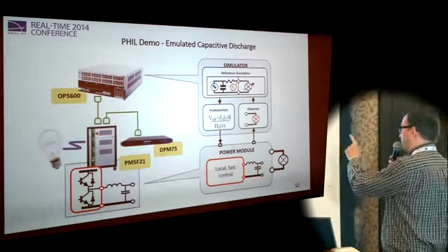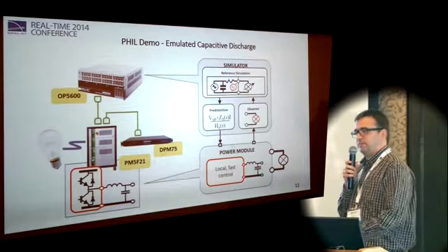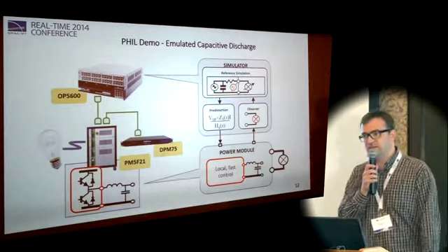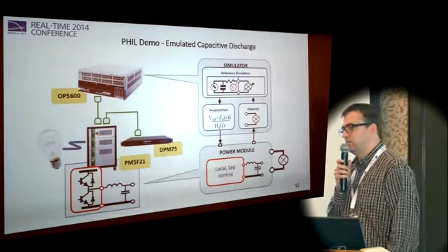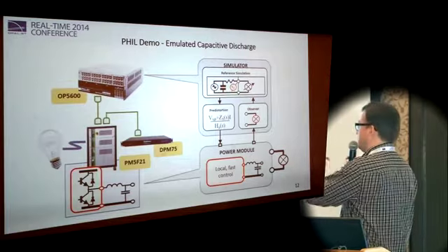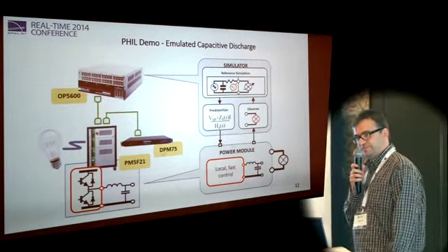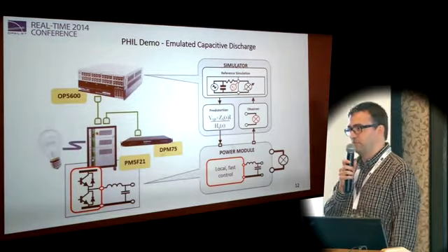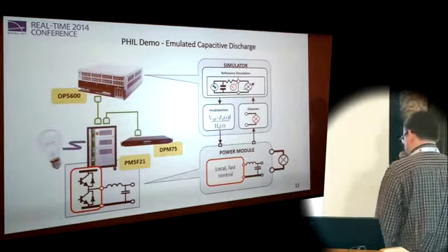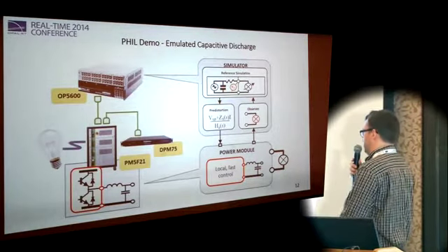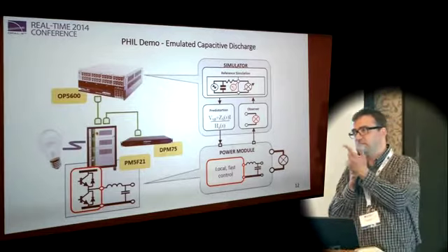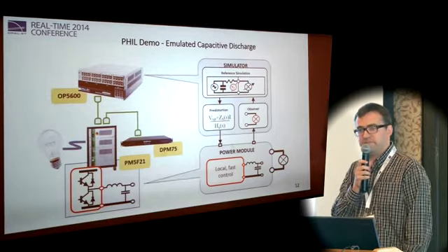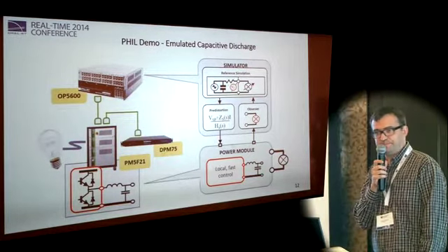But if you use the capability that the simulation is able to look into the future, then you can easily bypass the delays that are involved in your amplifier and compensate for other non-idealities of the amplifier by taking them into account in your simulation model. That's a very easy way, and it borrows from the ideas that you have in model-based control. So we make an observer, we align the simulation with the measured results, then we simulate a little bit into the future, and that's an easy way to bypass all delays that are involved in our system, and you have a perfectly stable power hardware in the loop solution.